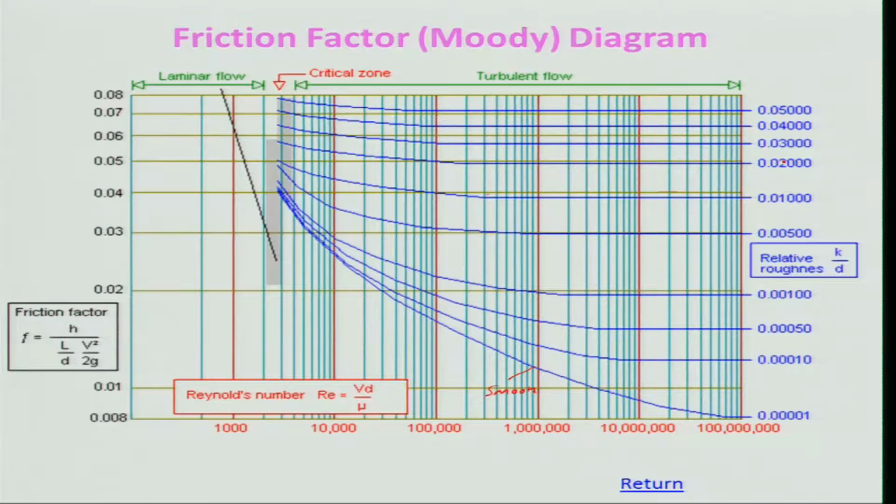Of course, with the increase in roughness the friction factor is increasing, but it is independent of the Reynolds number in this regime. As the friction factor increases, these regimes are increasing, and you can have a region, something like this, where it will remain constant. In this region, it is independent of the Reynolds number. That means if I look at one kind of pipe, the friction factor won't be changing, it is no more dependent on the Reynolds number. So, getting these values I can estimate f, and getting the f value I can proceed.